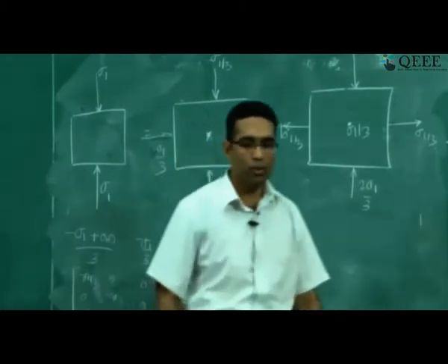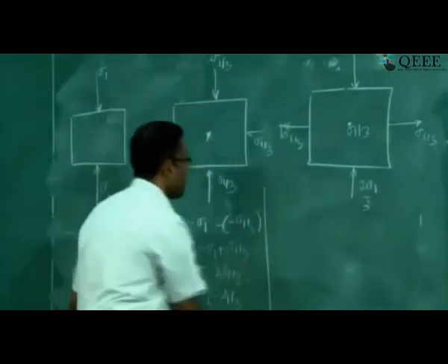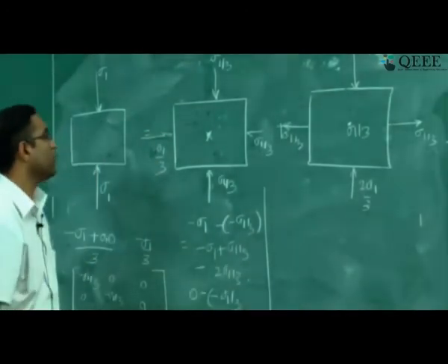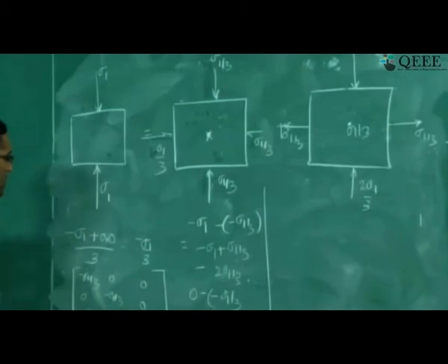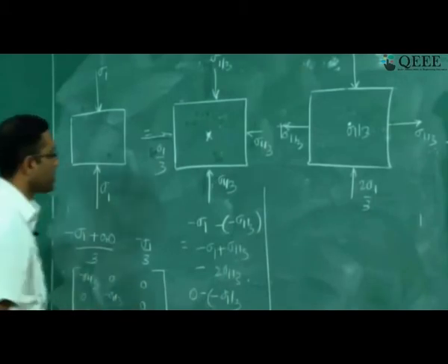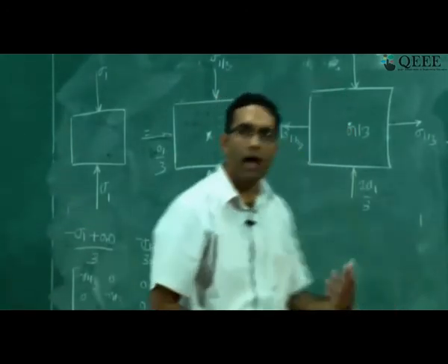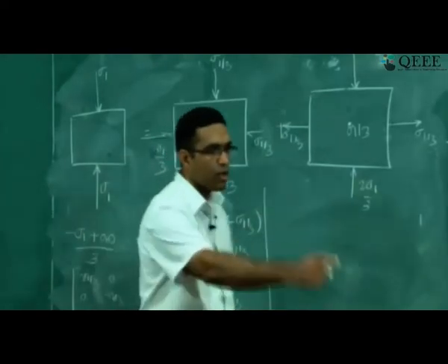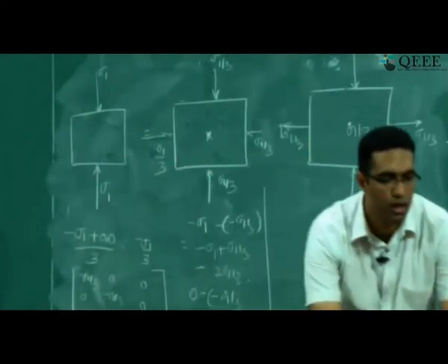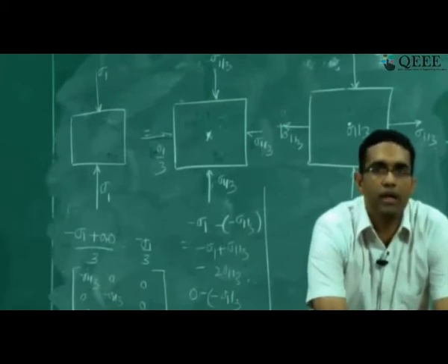So now we come into the various theories of ductile failure, because this is what is important to us. Before that, I'd like to point out that just like how there are invariants for the stress tensor, you can have invariants for the deviatoric component of the stress tensor. The deviatoric component of the stress tensor is equation 13 on slide number 11. You can write down the various invariants in a similar manner.